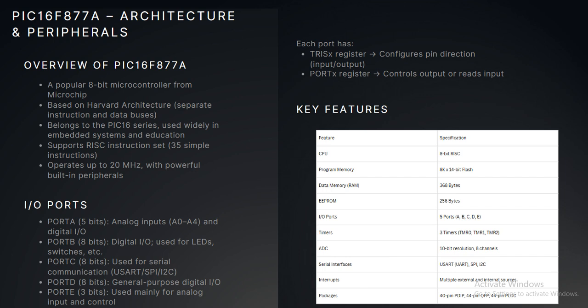And then next we will see the PIC16F877A architecture and peripherals. The PIC16F877A is an 8-bit microcontroller from Microchip. It follows Harvard architecture, uses a RISC instruction set and runs at up to 20 MHz.